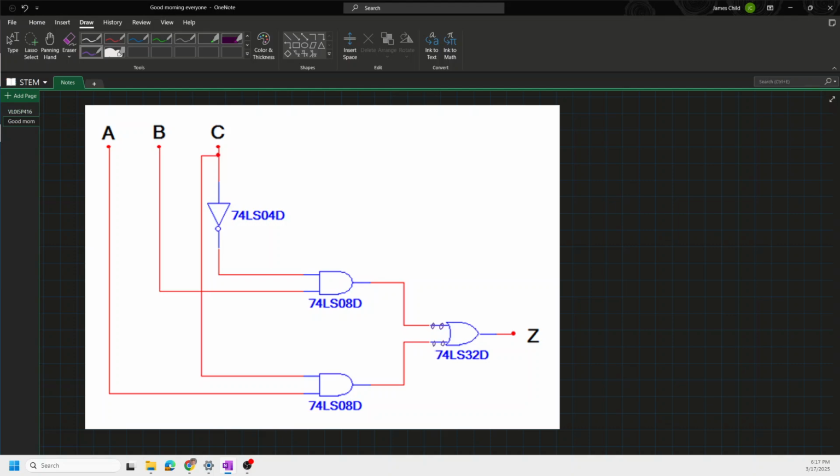Okay. First thing I'm going to do is I'm going to push this one and this one back to these AND gates and make them OR gates. Okay, so I've got an inverter bubble there and an inverter bubble up here, and so those become NAND gates right off. That means these two are gone. But that means I have an inverter here and here.